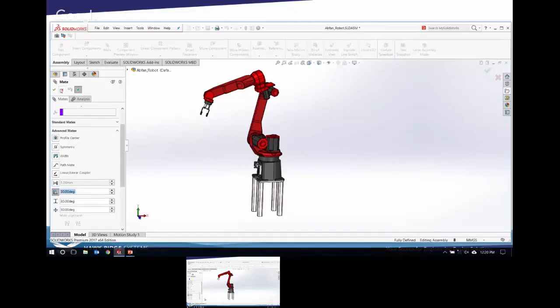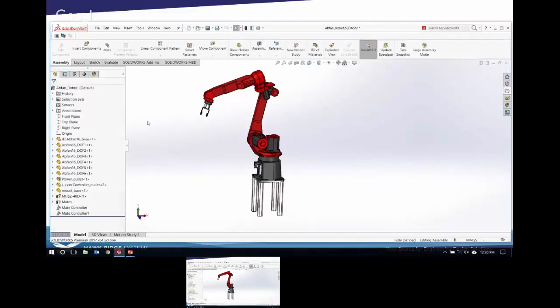As far as picking up an object, I guess you could define like a distance mate between the gripper and the object, and you could tell it that you're going from certain maximum distance to a zero distance as you bring it onto the canister. So you could set it up something like that.